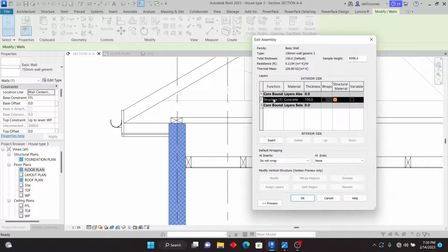Maybe I'll start with the outer wall, outside here. What do I want to have? So I'll change this one. Let me change this one. I'll maintain the structure the way it is, and I want this thickness to be 140. So that is the thickness for the outer part of the wall, which will have a veneer on the outside. Now the next layer that I want to have is, of course, let me have a layer of another 140.